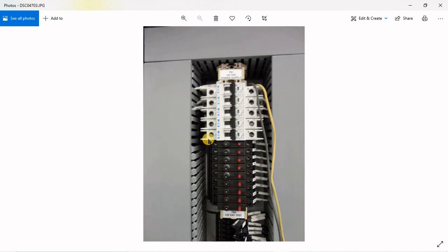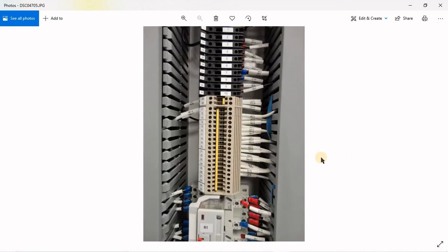You can see here, as we said before, the distance between the terminals here and the wireway is very small, so it's very tough for those guys, but later on, you can see it's okay. We don't have any issues later on. So again, the problem would be if you increase it, you may go over the size of the cabinet too much. So sometimes you play with these things.